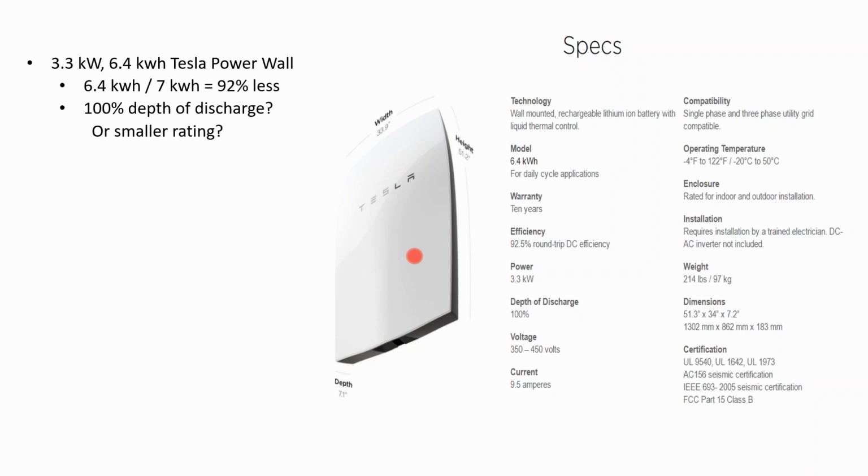You're not able to supercharge your battery performance, which is a feature that, if you want to be able to damage the battery through rapid discharging beyond what it's listed for, is a solution you would have to piece together by separating the inverter manufacturer from the battery manufacturer. And at that point, the battery manufacturer may not honor their warranty. They may ask you for the voltage rating and temperature logs of the battery and say, oh, you were running this battery out of spec, and we understand why you were doing that for cost savings, but it voids our warranty when you're using it in this manner.